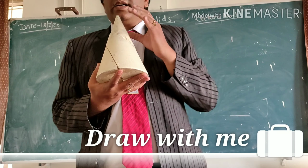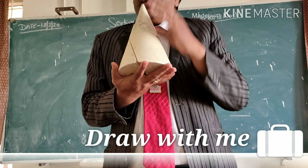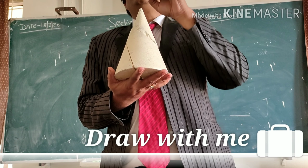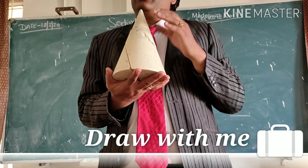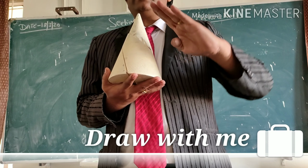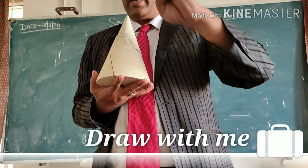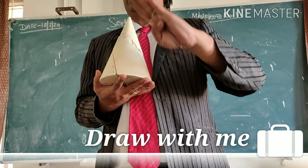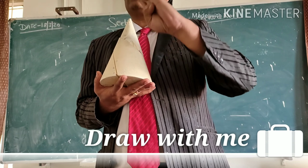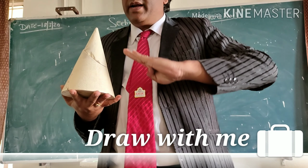So this is a cone resting on HP on its base, and when it is resting on its base, what is the position of the axis? The position is perpendicular to HP and parallel to VP. Now we are cutting this cone by a plane. I have already explained that a solid can be cut only by a plane, and we are cutting this cone by a plane which is inclined to HP and perpendicular to VP.